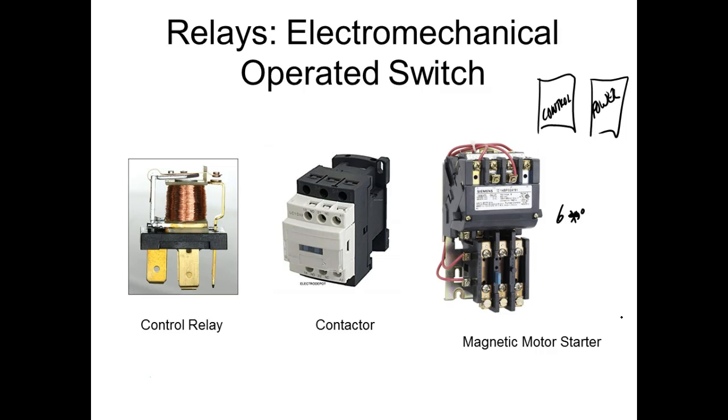Most of these relays have what we call a manual override on them. You have to be real careful about using these guys. So what you just did is you've taken away every safety procedure that's built into your automated system. We had a guy at US Steel got killed when I was out there. A guy went in and overrode the wrong relay.